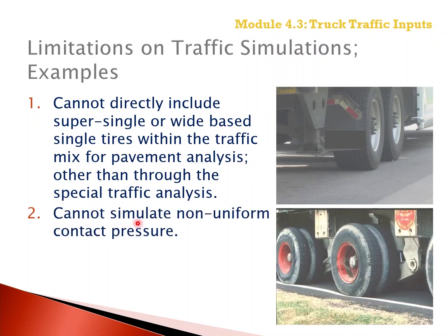The Pavement ME cannot simulate non-uniform contact pressure, which we know we have with the super singles and our wide-based single tires.